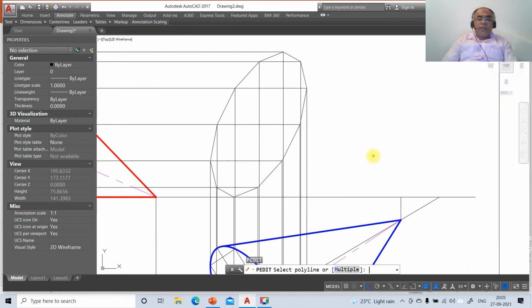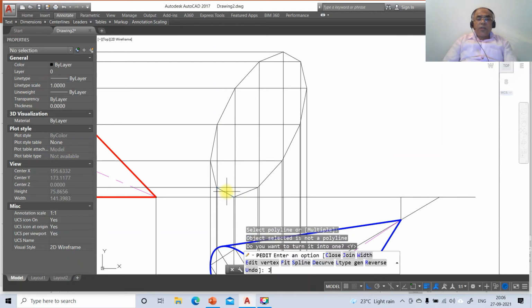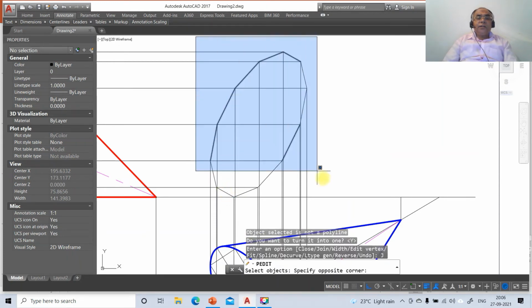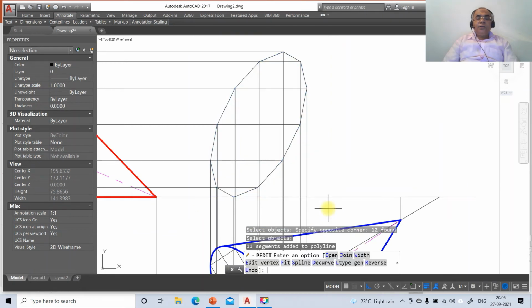Now you just go to pedit, select this, so enter, join. So you take this entire drawing.